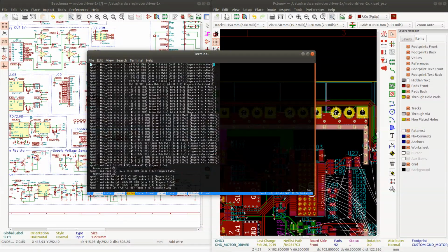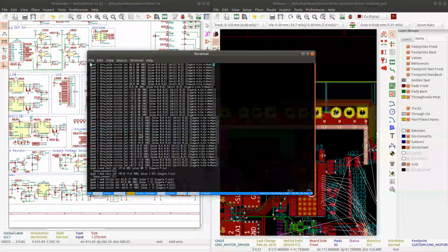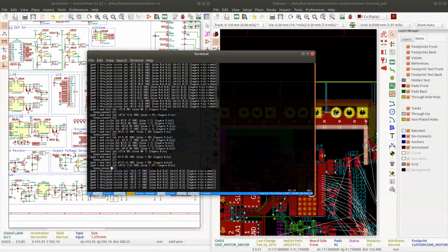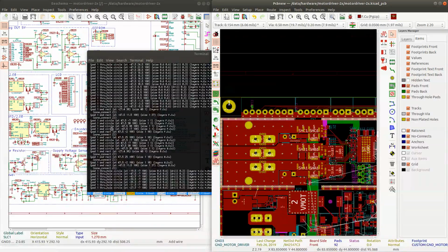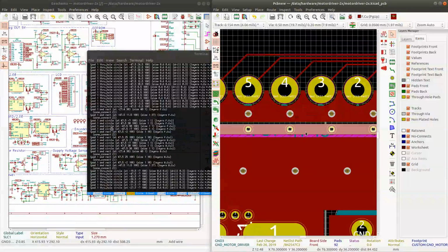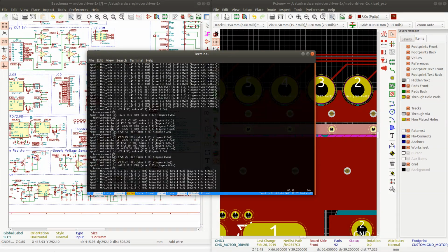The way to find out what settings need to be changed is basically just by changing something in the editor and then looking at the difference that it makes in the footprint file. So, for example, to make sure that we have solid connection to the zones for some pads, which is actually going to be all of the pads here. I want all of the pads in this footprint to have solid connection to the ground, because this is essentially part of the ground plane. So to ensure that it's solid, I can set the zone connect to 2.